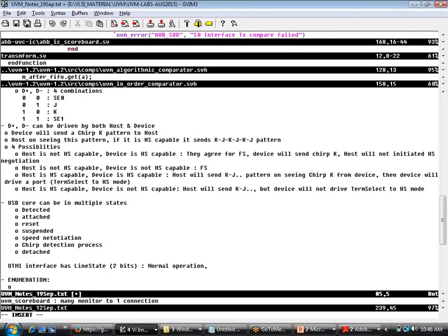Whenever you connect any pen drive or any USB device, you see that the device gets detected automatically, right? It will detect the manufacturer name, the type of device, the memory, and any other characteristics that are useful to the user. But there are also internal things, like how many endpoints there are, the type of endpoint, whether it's an IN endpoint, and the direction of the endpoint.